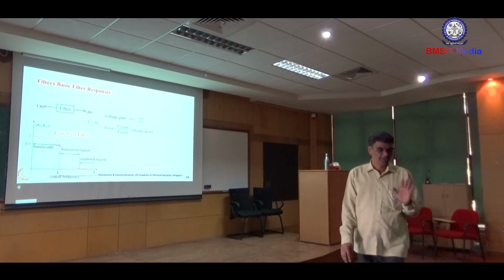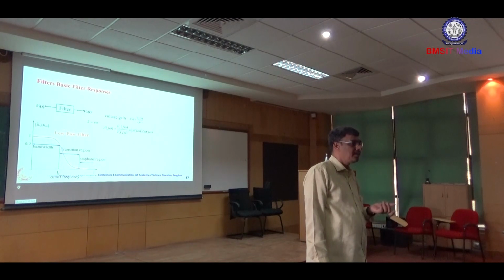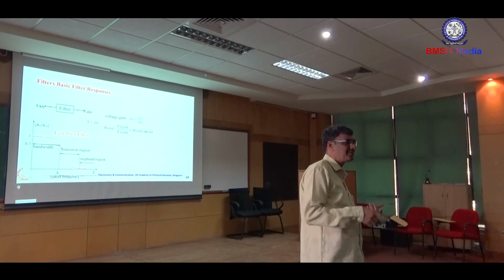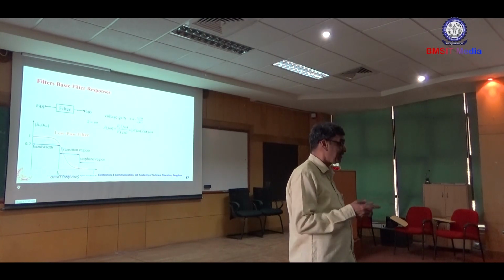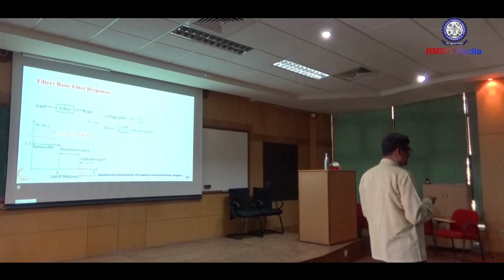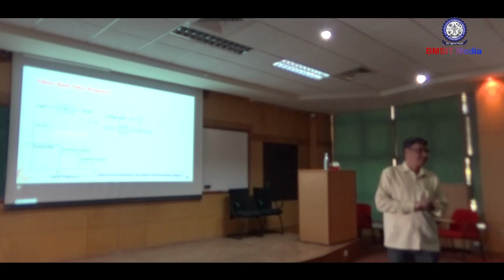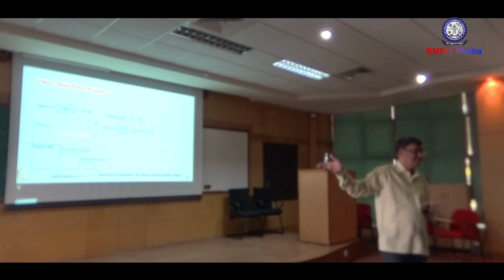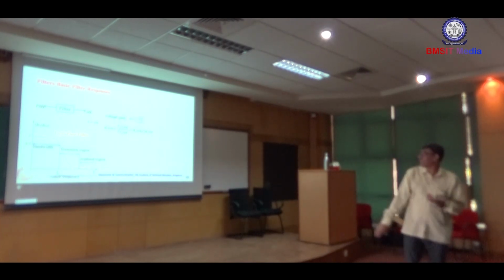Normally, when you are doing that relation in time domain analysis, V0 and Vi are related by using a convolution integral. I hope this is one of the properties studied in Laplace transforms, the convolution property. Recall mathematics. If two signals are convolved in one domain, then it is multiplication in the frequency domain or the Laplace domain. Therefore, based on that, you have defined that AV is equal to V0 by Vi.